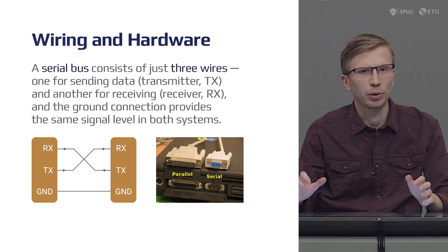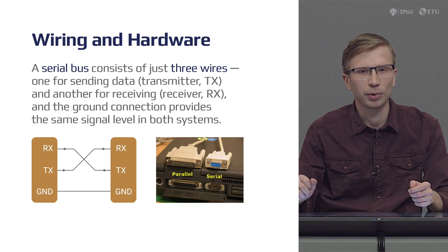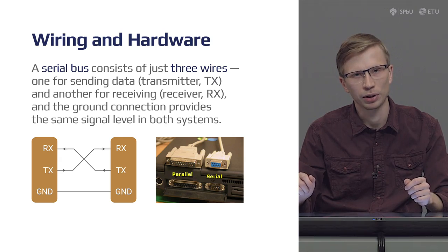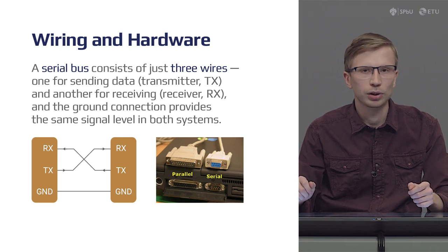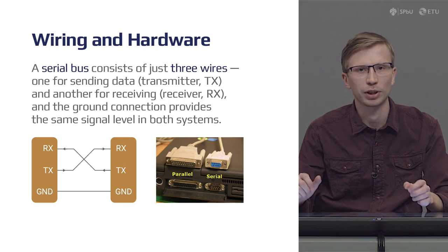In contrast to a parallel port, where all 8 bits of a byte are transmitted in parallel, all at one time over a cable with 8 wires, a serial port needs only one wire to transmit 1 byte. Bidirectional communication allows each device to receive data as well as transmit it, as serial devices use different pins to receive and transmit data. So this makes a serial port suitable for full duplex communication, in which information can travel in both directions at once.